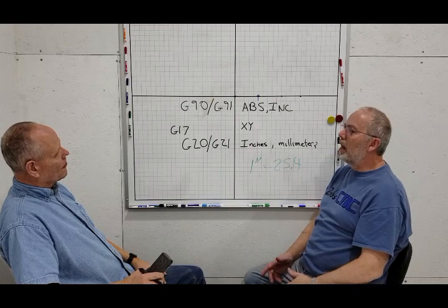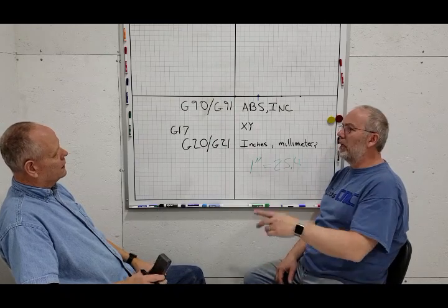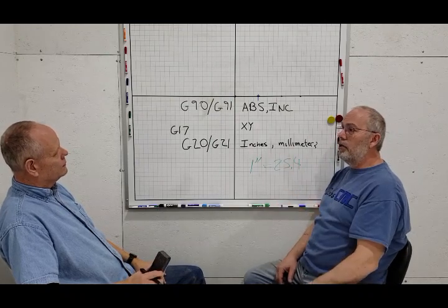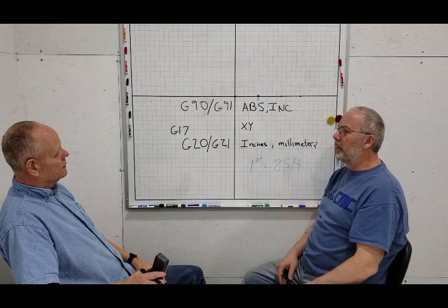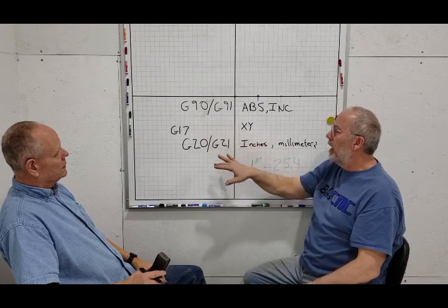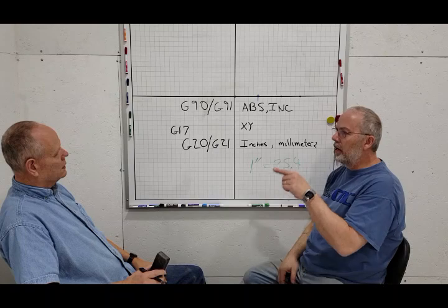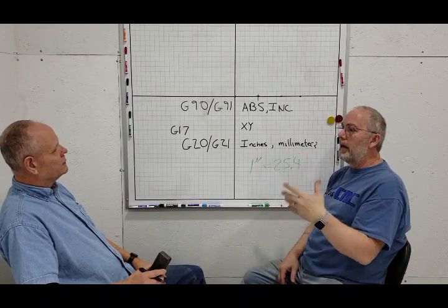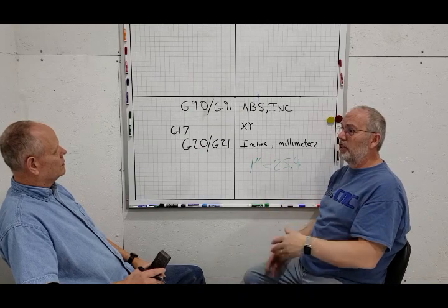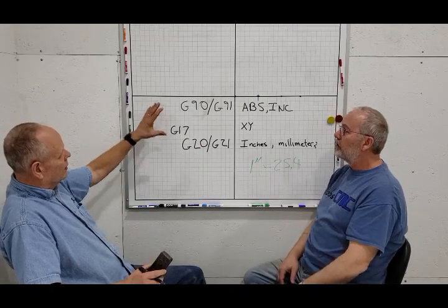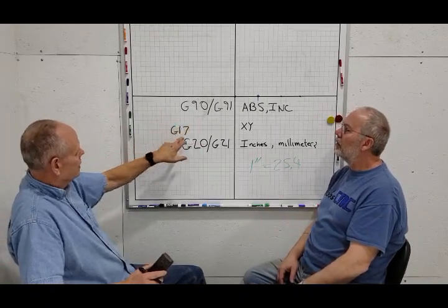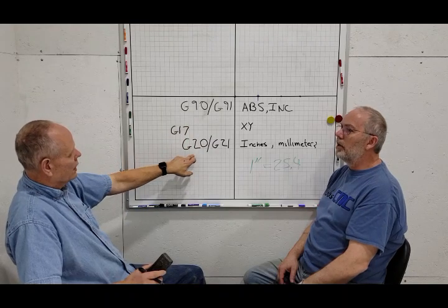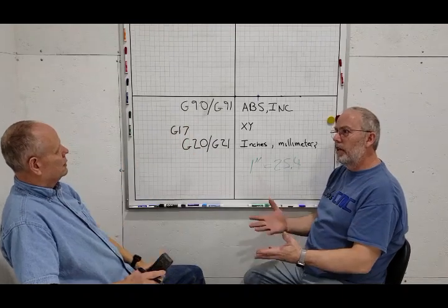So if you wrote a block that was 1 inch by 1 inch by 1 inch and you did a square, and then you ran it without the G20 or the G21, it would default to the G21, and you would go 1 millimeter over, 1 millimeter over, 1 millimeter over. Okay. And a millimeter is about 40 thousandths of an inch, so it would be really small. So the basic three I'm going to see are G90, G17, and G20 or 21, depending on what units you're in.